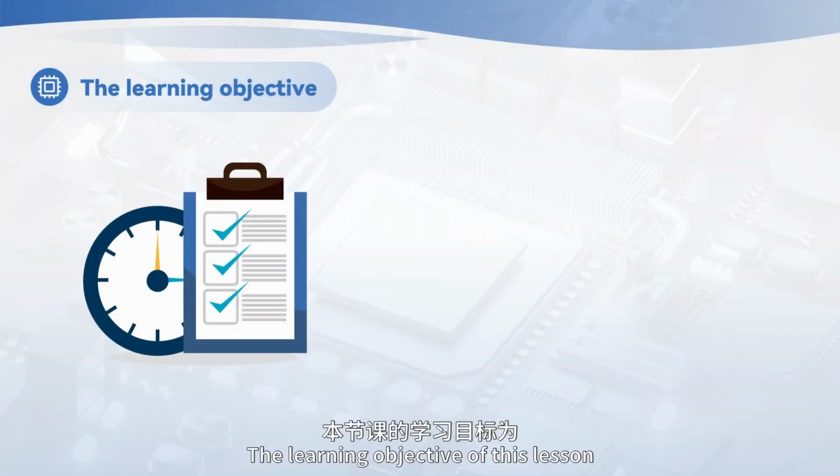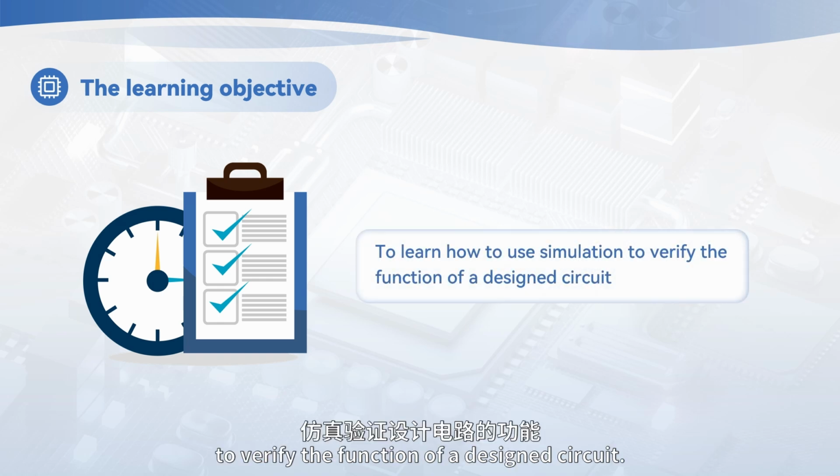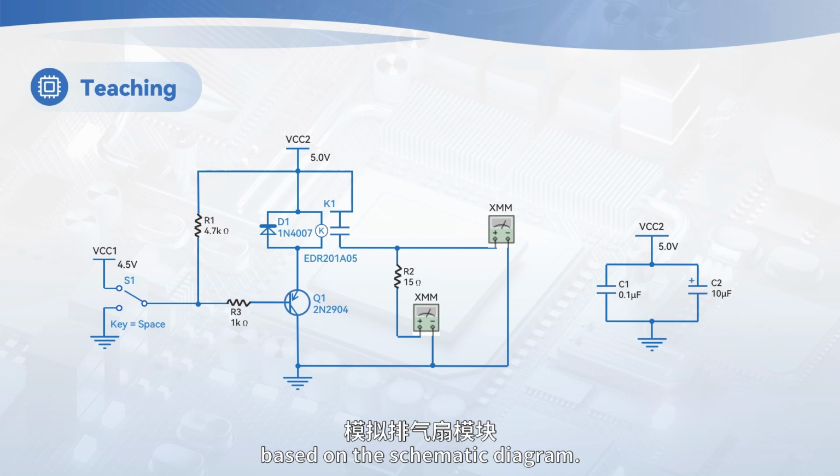The learning objective of this lesson is to learn how to use simulation to verify the function of a designed circuit. This simulation experiment is to design the exhaust fan simulation module based on the schematic diagram. When a high-level input is applied, the transistor is in cutoff mode, the relay does not engage, and the output voltage is 0 volt with an output current of 0 ampere.